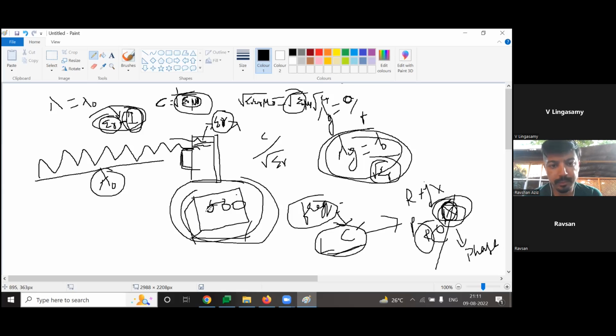The complement of this will be, you will not have any material, you will just have metallic posts. So here it will be via holes, but here you will have metallic posts. The gap between them is going to be air basically. So this also causes a variation in the dielectric constant, the effective dielectric constant. So why am I calling it the effective dielectric constant?